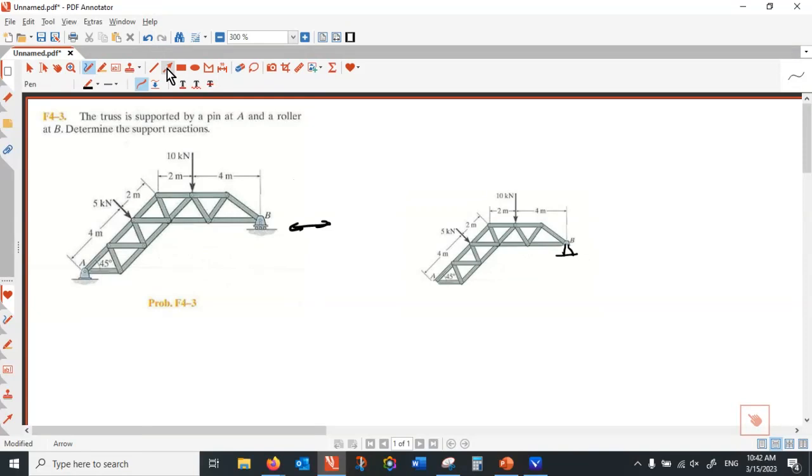So here, let me expose the reaction force here. The reaction force was there before releasing, but that's hidden. I didn't need to worry about that. When I cut it, it becomes live. It has to be exposed. And now, if I release A, how many forces would be exposed over there? That's a pin support. Two, yeah, okay, two forces there. And we don't know the direction, that's okay. We assume that they are in the positive direction. Later on, we might be proven wrong.